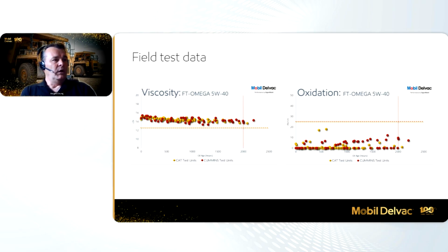We can see that viscosity laid in there really nice. We don't even really see a lot of initial shear with this particular product, and it is extremely shear stable in that it just stayed flatline, solid, right out to 2,300 hours, or 2,250 hours, somewhere in there. So that was extremely impressive.